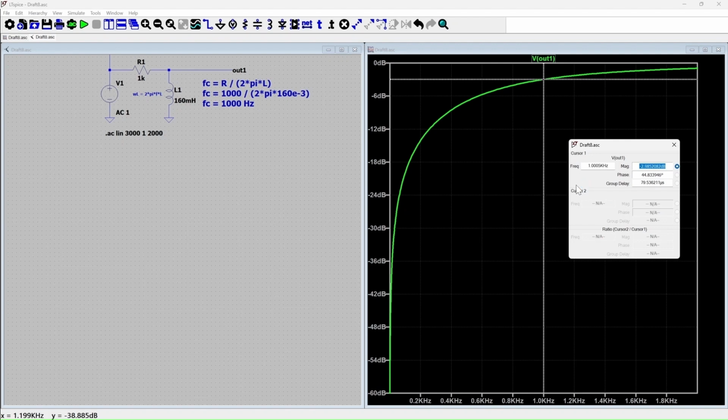Now our attempt here is, as I mentioned earlier in the tutorial, inductors are not preferred in audio circuits for various reasons. Firstly, their behavior is non-ideal. Secondly, they are bulky. Thirdly, they are costly. Fourthly, they have saturation-related issues. So we have to find some way to replace this inductor with an equivalent circuit. So what can that be?